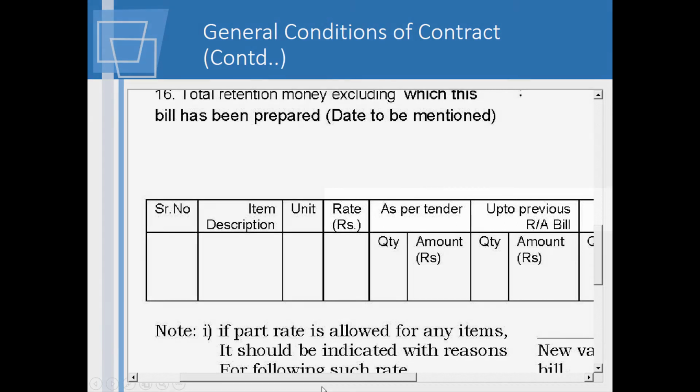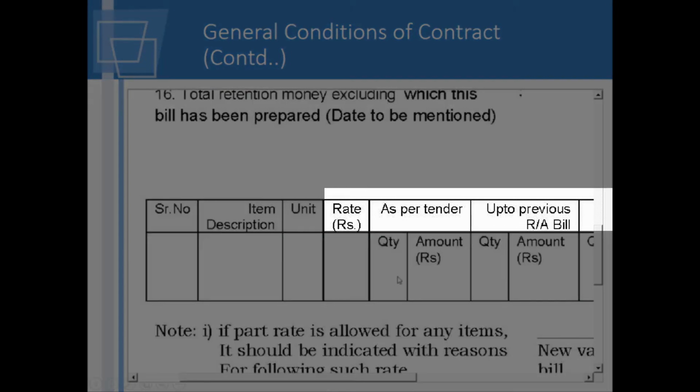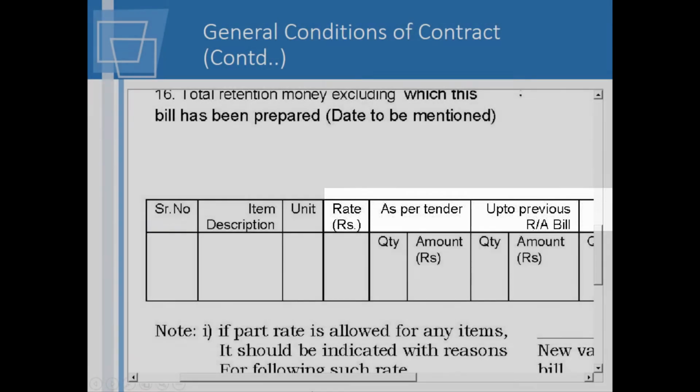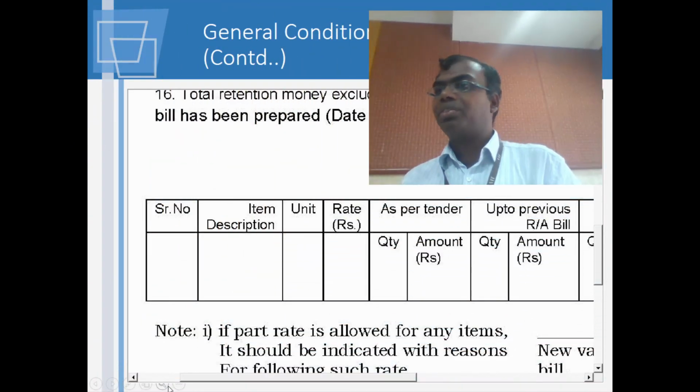If it's a running bill, this quantity is what is fixed. For example, if they say there is going to be 100 meter cube of concrete for the first floor, 100 meter cube of concrete is frozen. The cost is frozen. For doing it at the first floor, you'll have to take more cost because you have more safety requirement, some lifting requirement, everything comes into the picture. That's why I'd like to highlight why the cost of concrete is different at different levels.